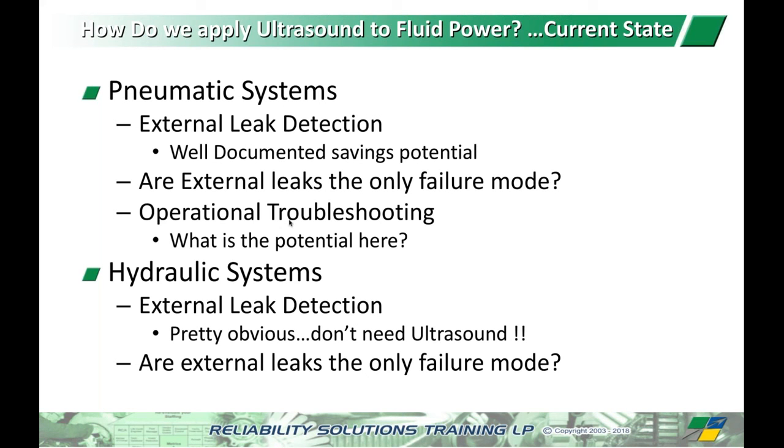So your operator basically presses the button, the stamping press rolls, and all the operator does essentially is take the stacks off the back end of the machine. So there's a lot of pneumatic pick and places going on, and obviously the timing has to be pretty good, because when you're stamping, your press is running at 360 strokes a minute. You got to get in there and snatch that little piece of aluminum out there pretty quick. And if anything kind of misfires, the results are usually pretty spectacular. It's like little ninja knives flying everywhere.